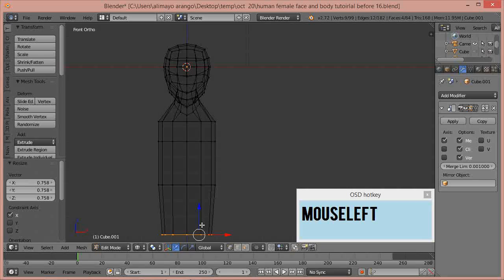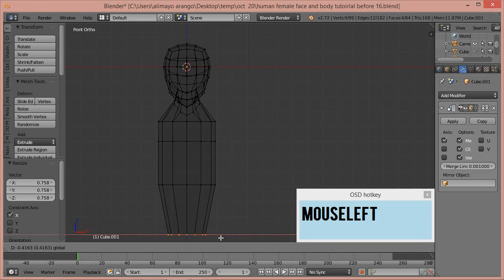That's fine, because with the mirror modifier on, you can actually push in to make things a little bit smaller. So if you start seeing it bunch up after you press S to scale on the X-axis, you can just go back and forth between that and using your manipulator right here to get the scale that you want.